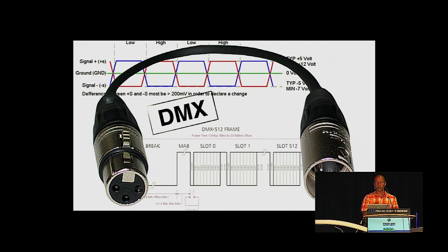So eventually it became serialized into this protocol called DMX 512, and it's able to address 512 individual channels of data in 8-bit slots. 512 channels is called one universe of DMX, because I'm sure it was the cliche of 512 channels has to be enough for anyone, right? No one's going to need more than 512 channels. Well, things grew, things got more complex, and eventually you have to run multiple paths of this serial cable to control more than 512 channels.